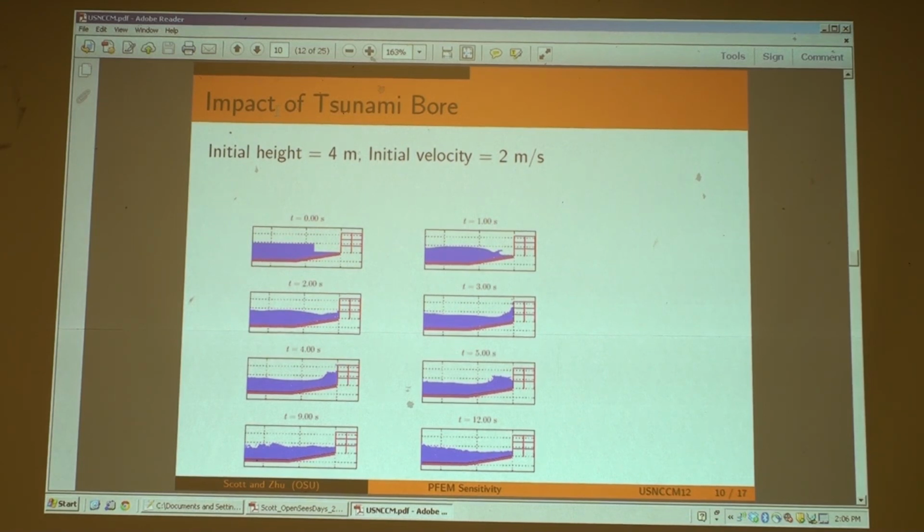I'm thinking your method may be useful for blast analysis, simulating with some blast calculation. Yeah, the particle method may be. That's something I haven't tried, but if you have a pressure history or something, you can put that onto the source and have a mesh with the structure. Or you could have some particles emanating from a source and blasting out at some velocity, impacting the structure.